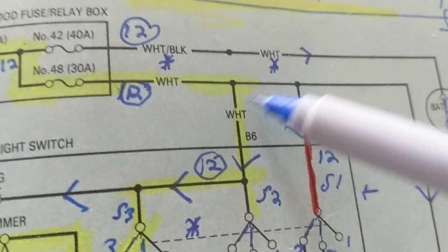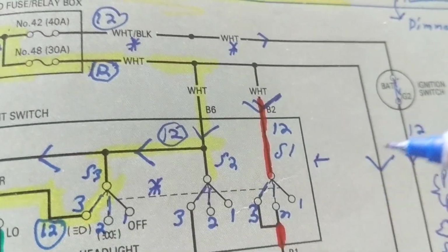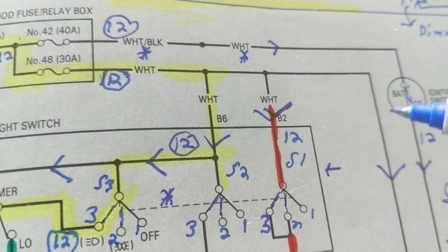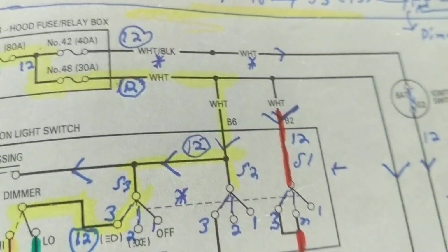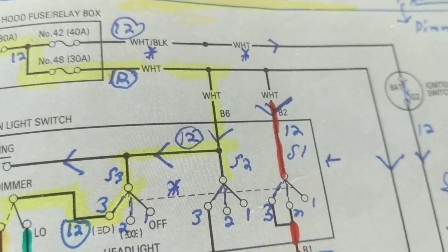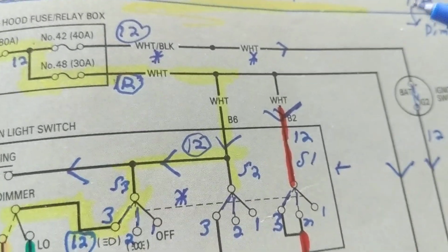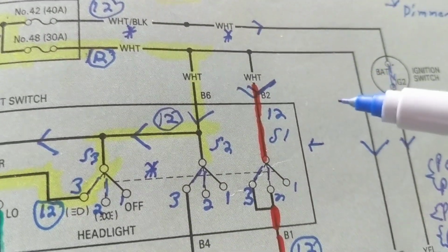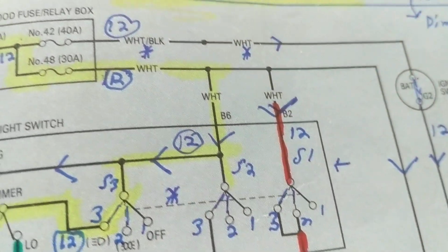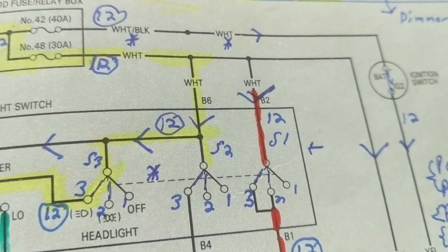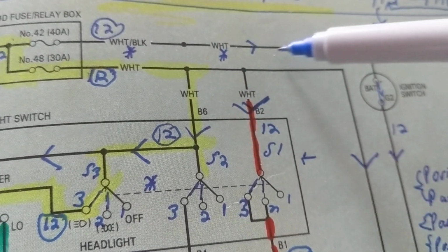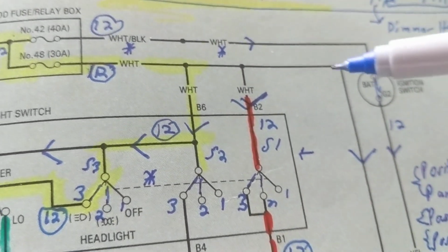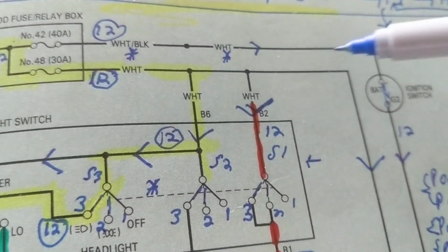The only time you're pulling current is when you have an appliance or a load connected to the outlet. That's why I always stress, put an ammeter to measure the alternator, not just look at the 14 volts. Put an ammeter, which I did a video on, to measure how much current you are drawing from an alternator. On that big thick red wire that says BAT, put an amp probe. And of course, I always like to put the fan blower on, because that draws a lot of current, 20 to 30 amps. When you have it at high speed, you get full voltage and much current. And I like to put the lights on and the fan blower, like I said, and all the accessories on. Let's go to the next point.